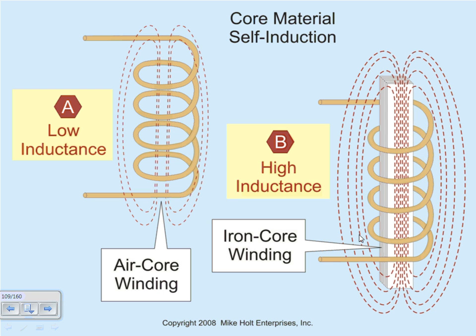So the strength of the coil becomes a big deal. If you have a coil that you're using for a magnetic contactor, you're energizing the coil, and when you energize the coil, it pushes two contacts to close. So the strength of the coil is a big deal if you're using it as a magnetic contactor. The strength of the coil is a big deal if you're using it for motors or transformers. So at certain times, you need the coil to be strong.